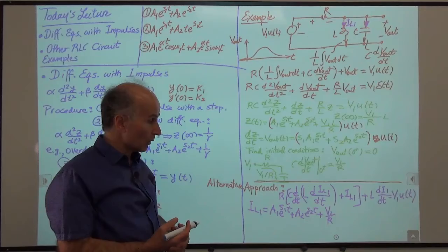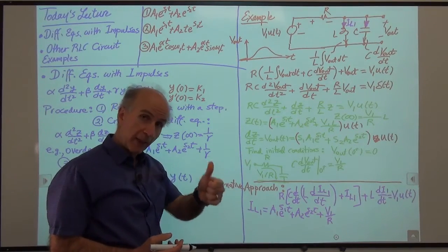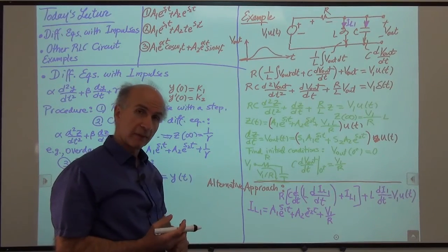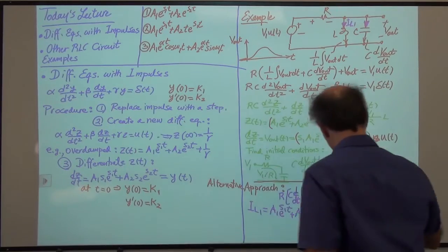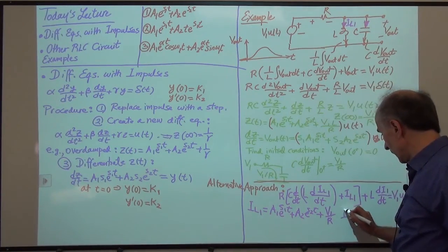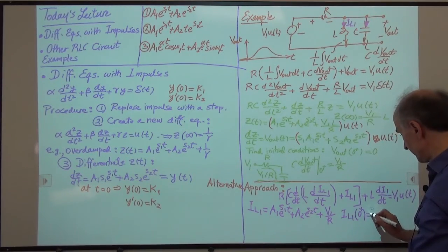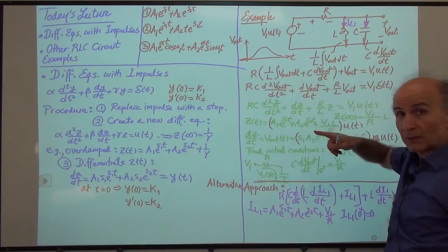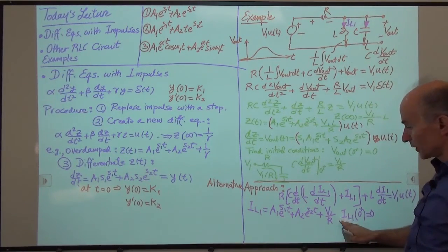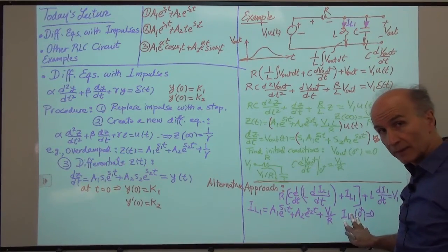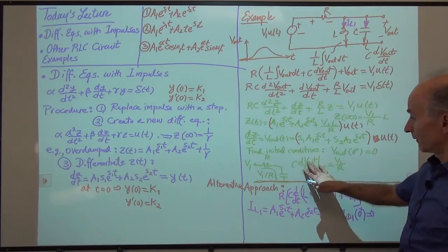Okay. So now we can solve the circuit. We can find A1 and A2 if we have the initial conditions for IL1. And we have those initial conditions, right? The first thing is that we know IL1 at time 0 plus is 0, because the inductor doesn't want to change its current. We've seen this before. And then we also need one more condition in terms of IL1. Previously we tried to recast that in terms of V out.